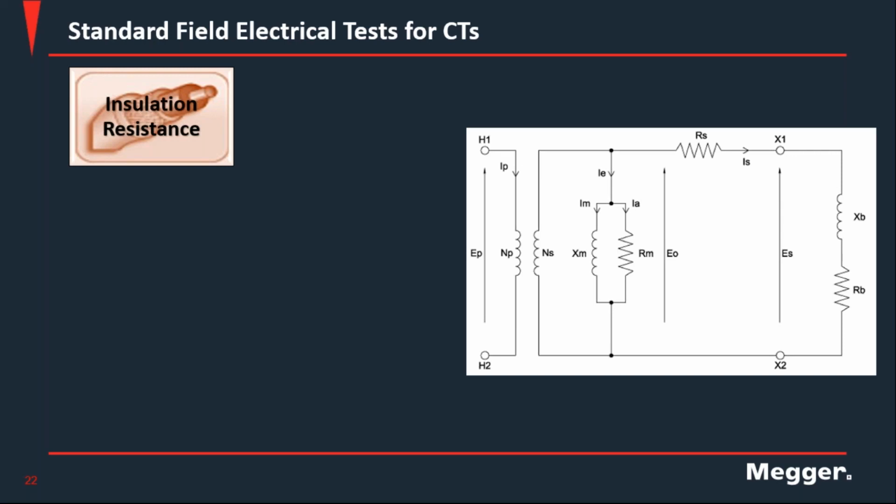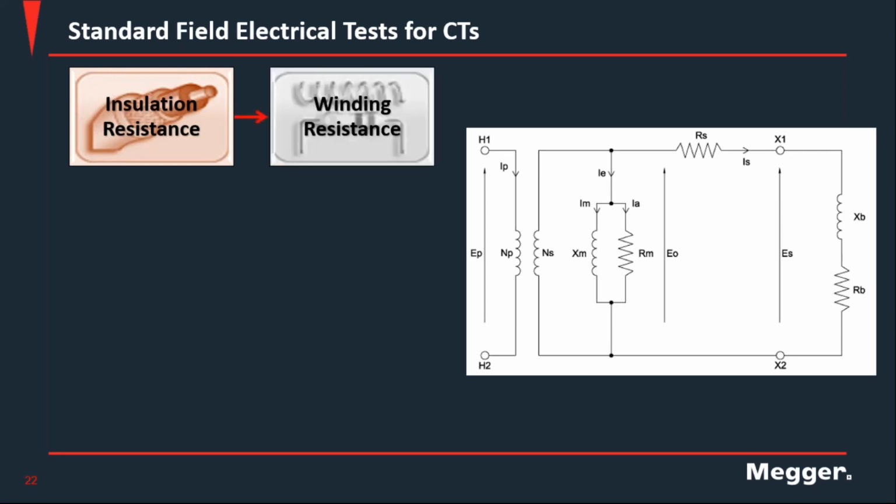But anyhow, the insulation resistance is a very quick test that allows you to determine if at least the transformer is still alive. The insulation is the life of any transformer. So if there are insulation problems, there's no point in trying to test the other parameters, because there's no actual functional transformer there. So this is not used for any assessment, but it's really important in the process of testing.